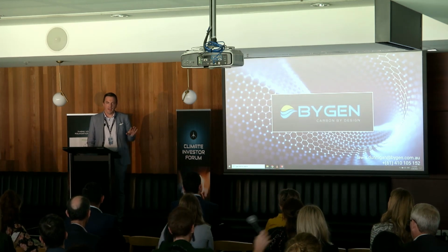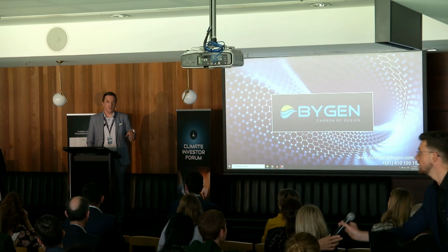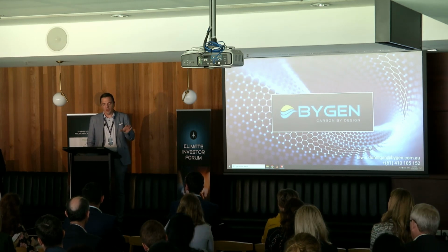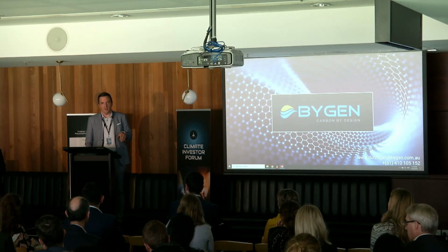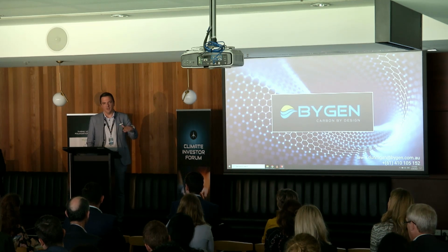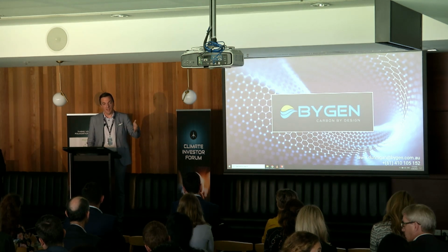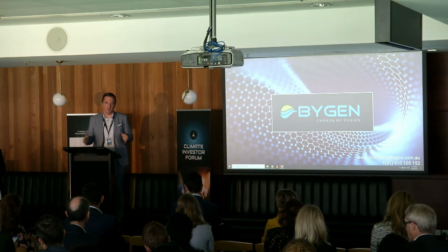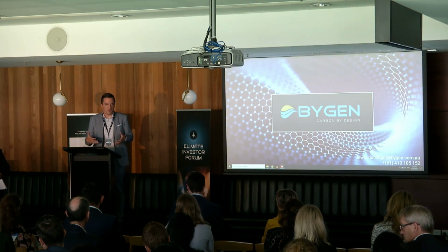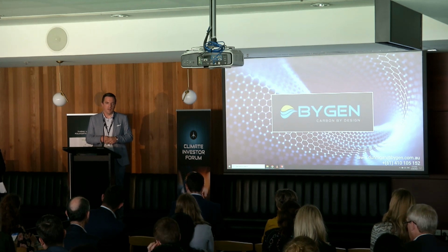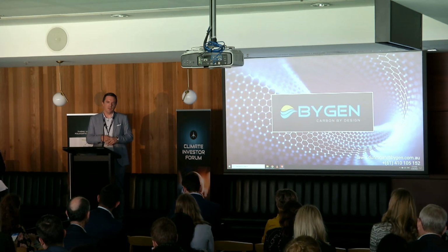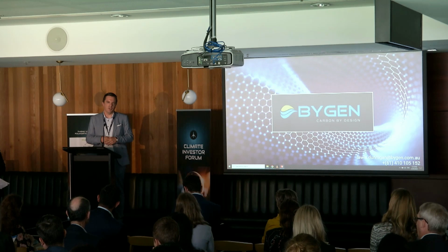So in Australia, that is one of the common ways of essentially disposing of it, but you are able to regenerate activated carbon by subjecting it to a pretty similar set of conditions compared to how you made it. So essentially you strip off and destroy whatever the contaminant is, and then you get essentially brand new activated carbon out of the same site. So it is possible to regenerate it. It's commonly done in Europe and America, but it's an emerging application in Australia.